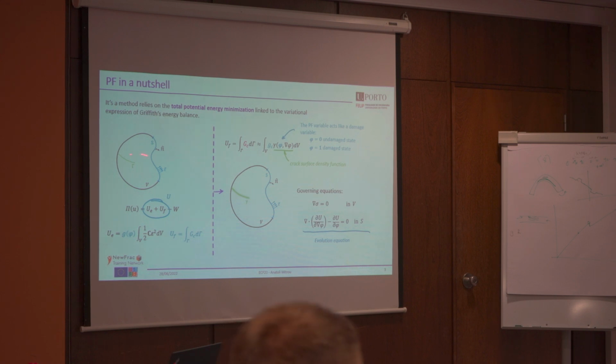It has an elastic energy term and a fracture energy term, and the fracture energy term has a phase field in it, which goes into the crack surface density function to represent the crack in a diffuse form, going from 0 to 1 on damaged state.